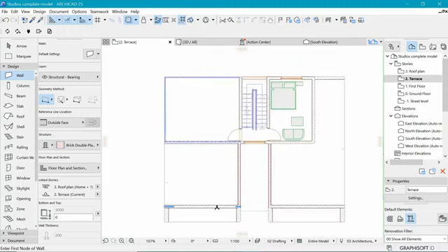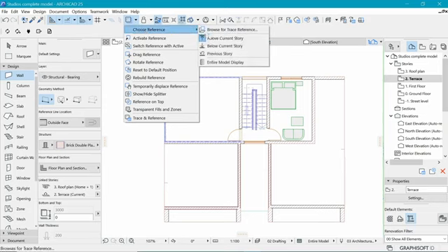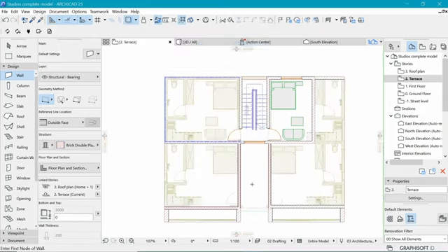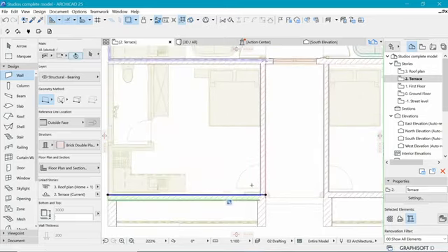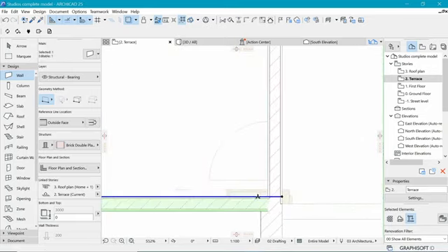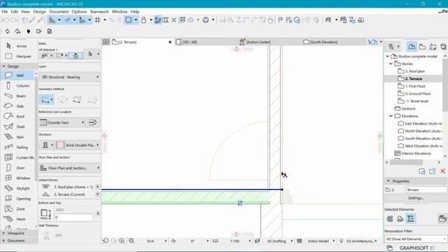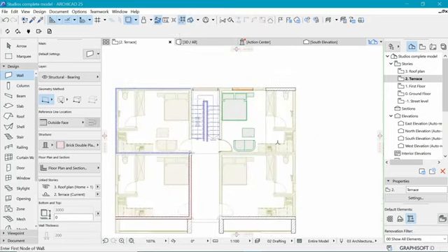Just to make sure that I'm doing the right cleanup, we need to be able to see the things below. So choose reference to be the below current story. So yes, this is what I'm talking about, such that this wall is really just on top of the one below. Yeah, so make sure that that is what you're actually achieving for those elements.